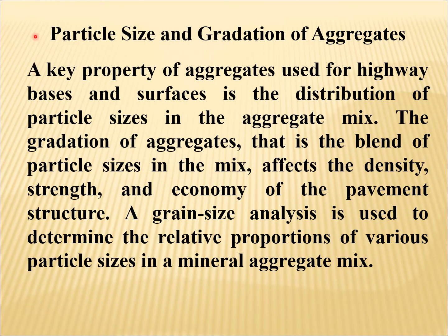First, look at the particle size and gradation of aggregates. A key property of aggregates used for highway bases and surfaces is the distribution of particle sizes in the aggregate mix. The gradation of aggregates, that is the blend of particle sizes in the mix, affects the density, strength, and economy of the pavement structure. A grain size analysis is used to determine the relative proportions of various particle sizes in a mineral aggregate mix.